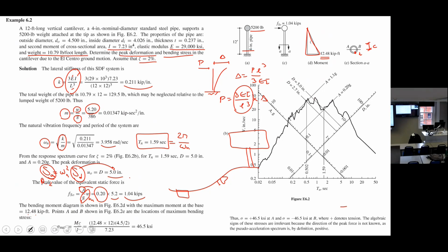What should we do? The answer is obvious. Go for higher strength steel, a higher class of steel. That can be one solution, but as I said, we want to stick with this kind of steel, and we don't have that kind of steel in the market for now. Change the cross section. Go for a bigger one, to have more second moment of inertia and decrease sigma.